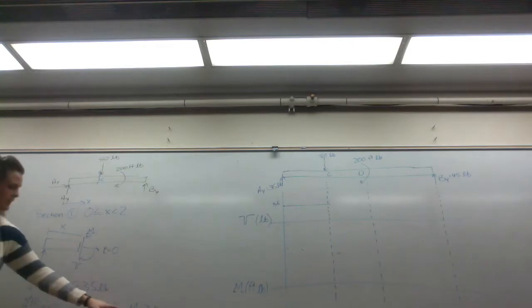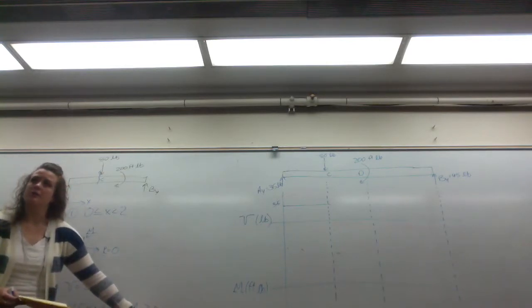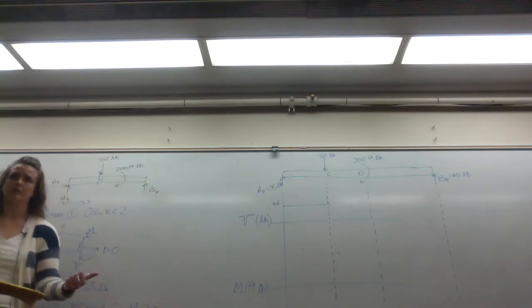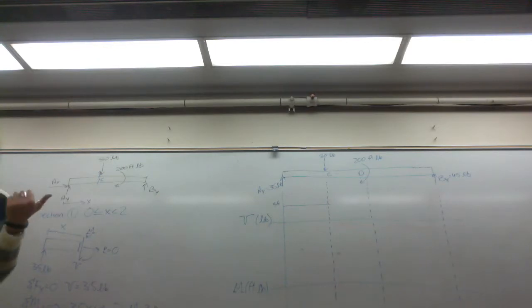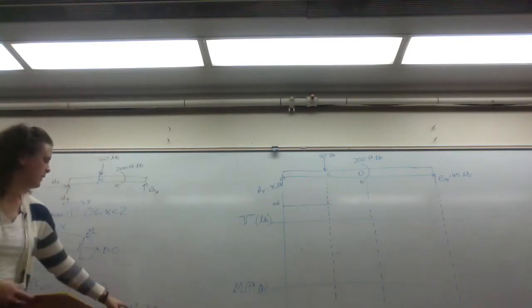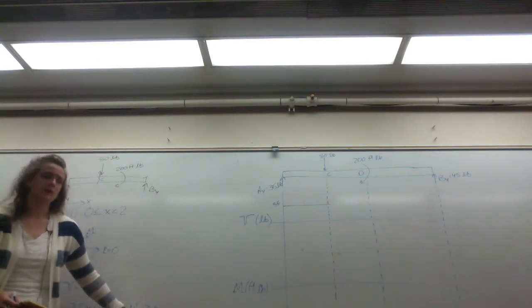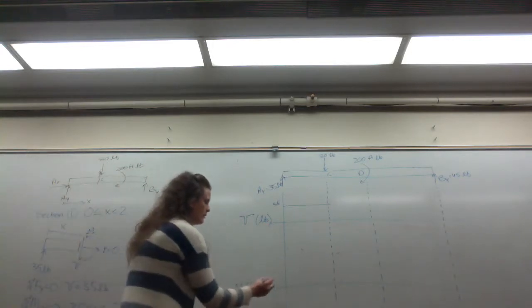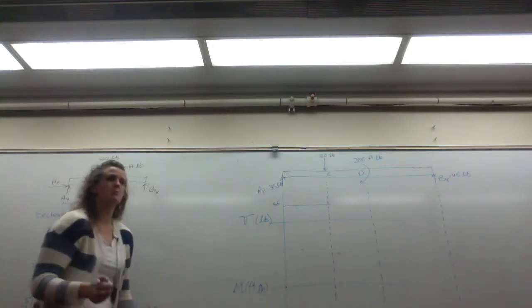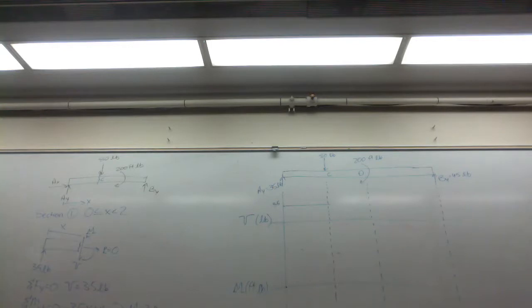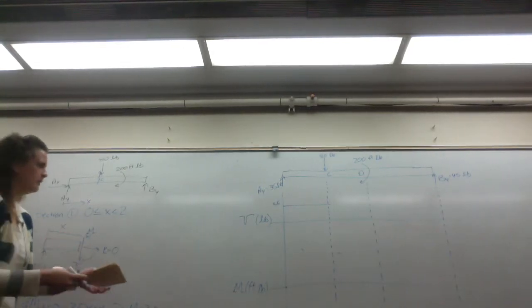But we can also look here in our equation for our moment. A first order is a positive slope of 35. So when x equals 0, our bending moment is 0, right? And that immediately needs to be the case. At any fixed connection, you can't bend, right? There's no internal bending moment.